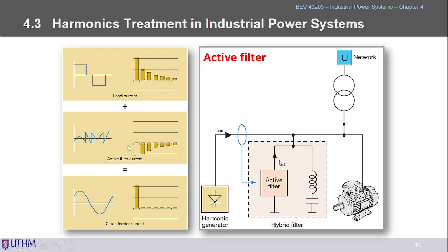So that's why we need to design the active filter so that it won't tune at the first one. The first one has nothing, but starting from the second one, it will be like the opposite. That means we need to generate the opposite waveform of the second, the third, the fourth, and so on, so that it will give the minimum value. At the end we will have the clean current like this one. We only leave the fundamental, right?